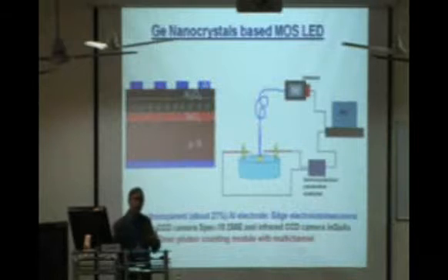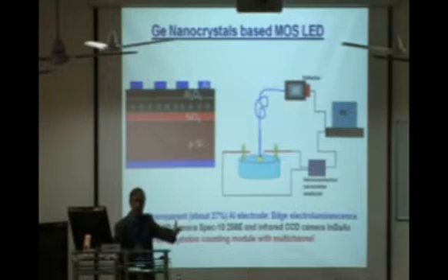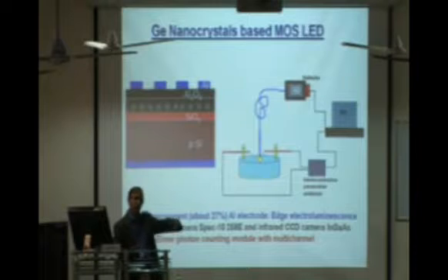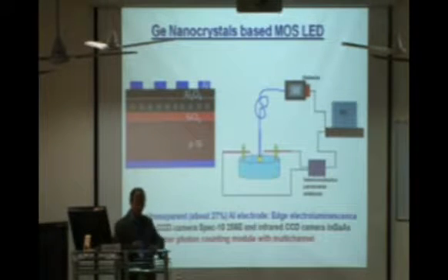Of course, for device people, the electronic engineers, you will not believe this photoluminescence. They say, can you give me some device where I will put a battery and the light will come on? That phenomenon is called electroluminescence. You apply an electric field, and if you get electron hole recombination, then the light comes on.